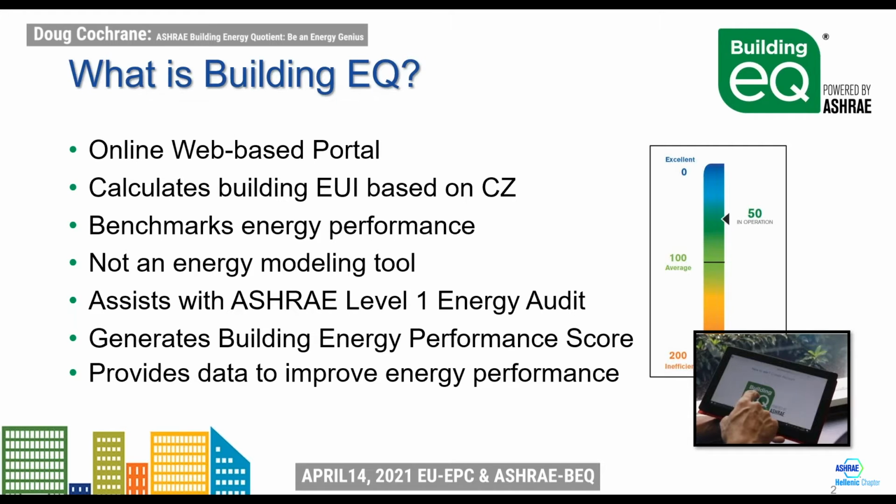Okay. So we've already said it's a web-based portal. So what it does is we calculate building EUI, energy use intensity, based on the climate zone. We benchmark energy performance. We are not an energy modeling tool. You would still do your energy modeling separately from Building EQ, and it assists with an ASHRAE Level 1 energy audit. It generates building energy performance scores and provides data to improve energy performance.